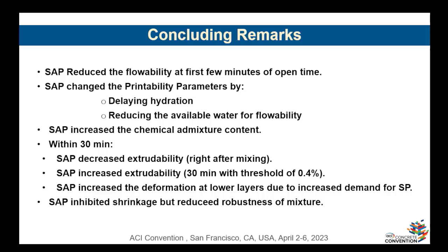SAP also increases the deformation of the lower layers. That's a problem. Controlling superplasticizer in favor of the viscosity is an issue. But our recent results show that SAP can inhibit the shrinkage due to evaporation. Still, like I said, I'm concerned about the reduced robustness of the mixture.